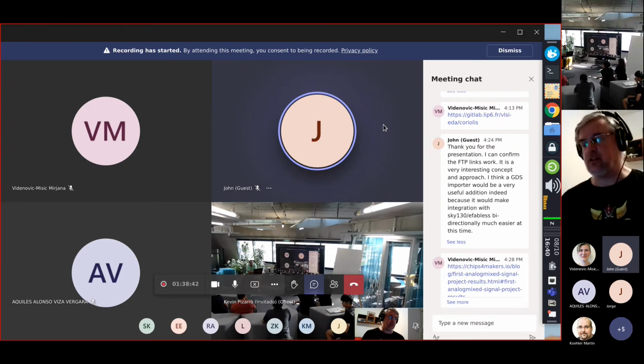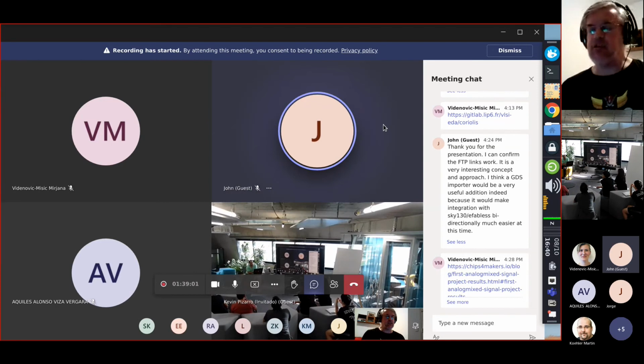Okay. Can we already map the electromigration equations from the technology to the Python scripting? So we just input a current and the tool gets the width automatically before the routing? No, you have to compute it yourself, but it's a Python script. If you want to write a Python script that makes that computation, that's completely doable. It's just a little script. You input your currents, compute the constraint, and give back a wire width. I see no problem in automating that.